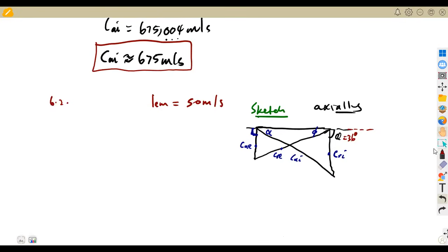So our blade velocity, U, is equal to 235 meters per second, which we are going to convert to centimeters using the scale that we are given. We divide 235 by 50 meters per second, which gives us 4,7. So we obtain 4,7 centimeters, which is the length that we are going to construct.